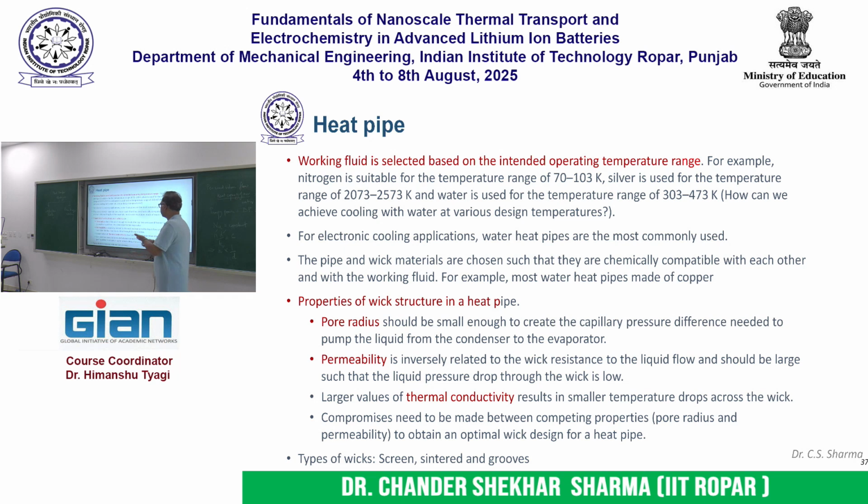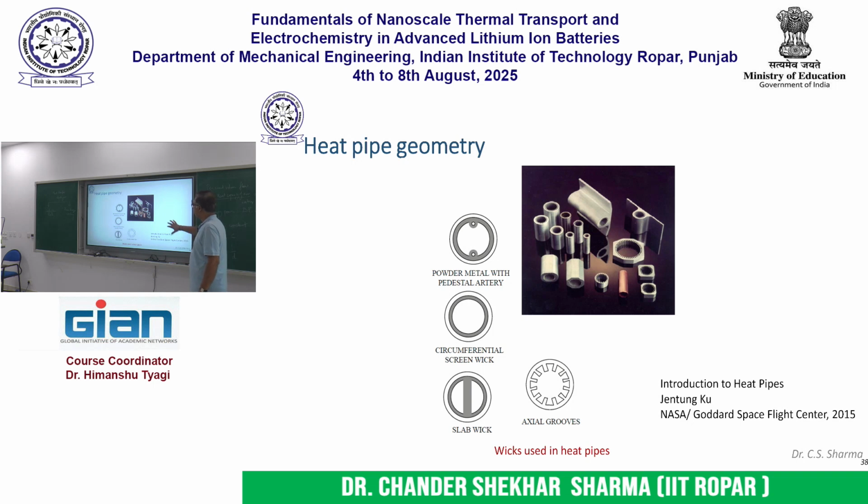And then of course the thermal conductivity of the wick material. We don't want the wick to be made of something insulating, which would defeat the purpose, so it has to be a high thermal conductivity material. But in general, compromises are made in these three parameters to maximize the overall performance. Heat pipes can have different geometries and different kinds of wicks depending upon the application.